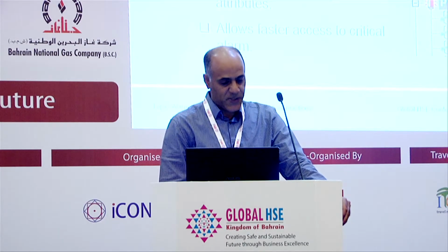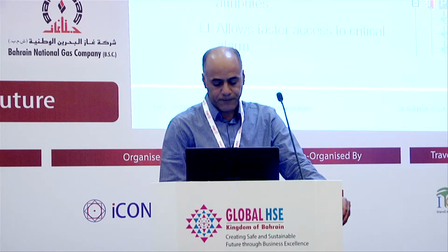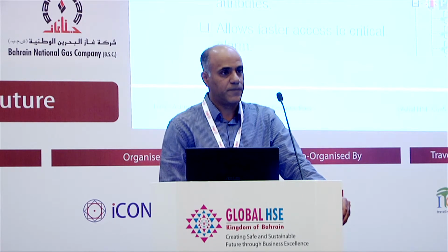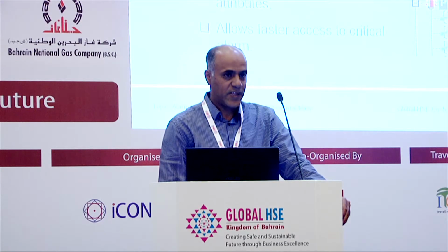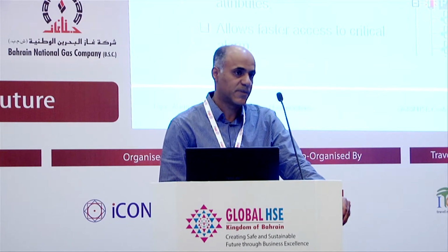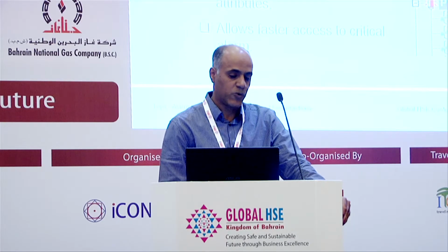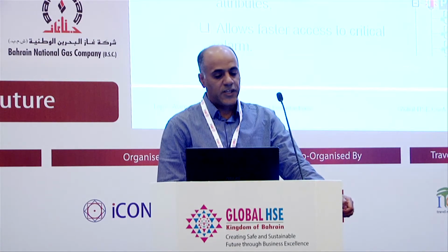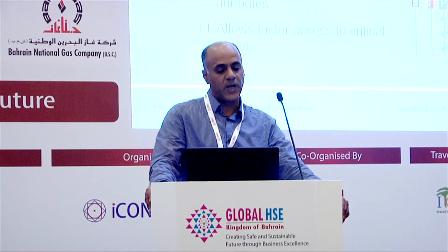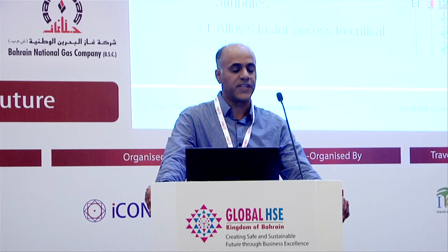And normally the best practices are targeting both the designers, the developers of the alarm management systems, and the operators. So if, for example, a company is going to buy a third-party alarm management system, they have to make sure that the alarm management system is complying with whatever is stated in the standards, one of which is having the capability of shelving alarms. Shelving alarms is the process of temporarily preventing nuisance alarms from being displayed for the operators.